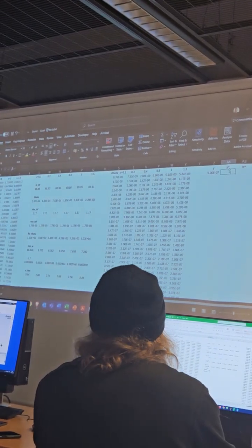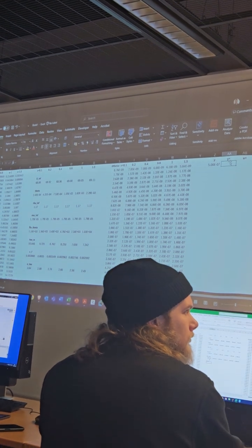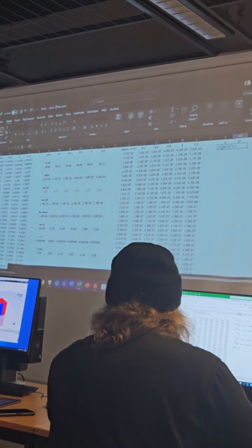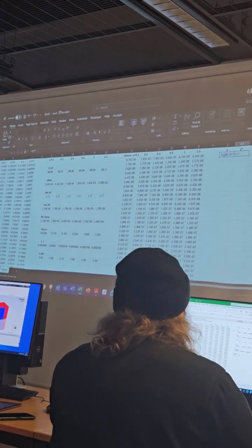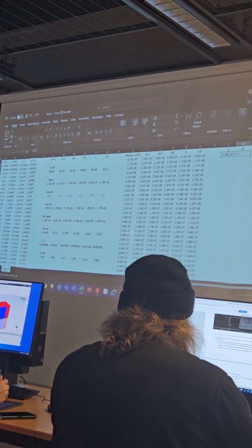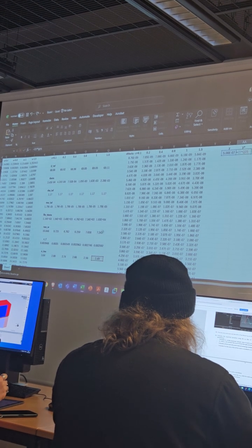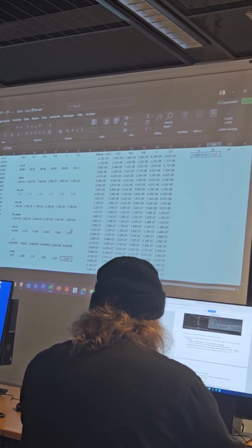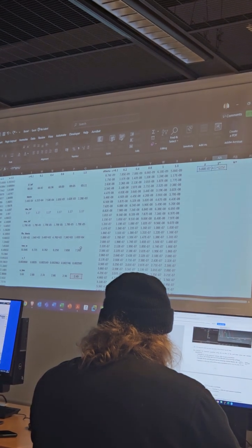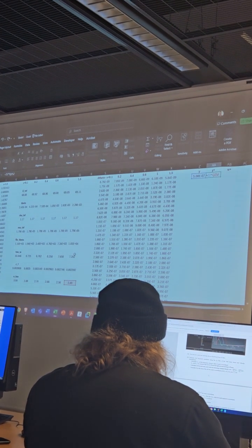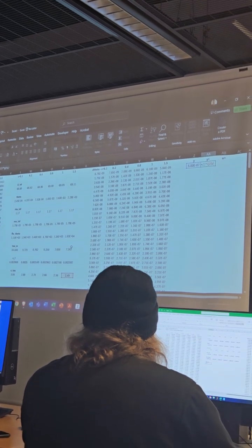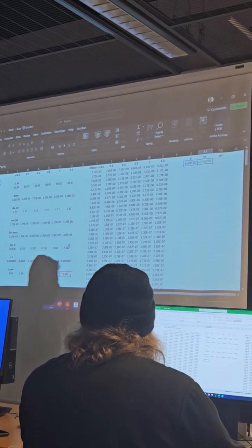Y plus is calculated with the formula y times u tau, the friction velocity, so we select u tau at x equal to 1.5, over nu wall. Nu wall is the kinematic viscosity, which is given here.